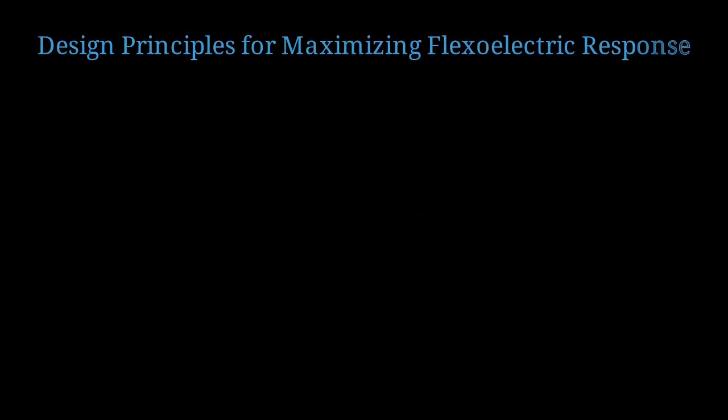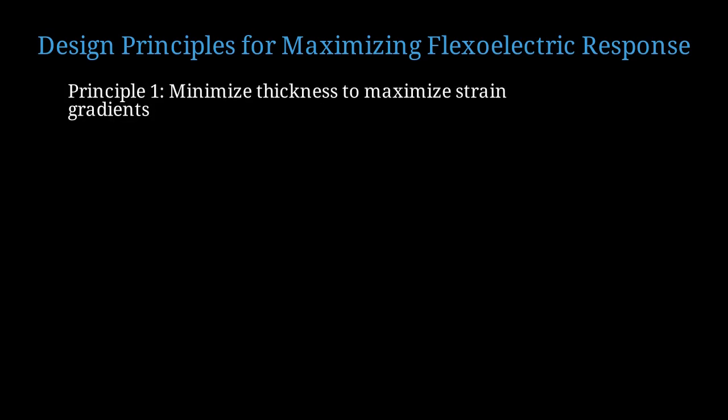Based on our understanding, what are the key design principles for maximizing flexoelectric effects? First principle: make structures as thin as possible. Reducing thickness from 100 to 10 nanometers increases strain gradients by a factor of 10.